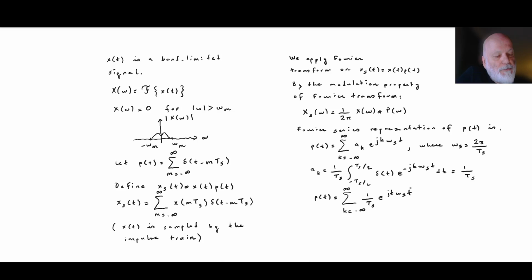So once more, we repeat an important observation related to this Fourier series. All Fourier coefficients are equal, even for arbitrarily high frequencies, for k in magnitude. We can choose k arbitrarily large in terms of magnitude, and those correspond to very high frequency components. So even very high frequency components are represented equally in the Fourier series representation, which in fact is related to the singular behavior of the impulses in the impulse train signal.